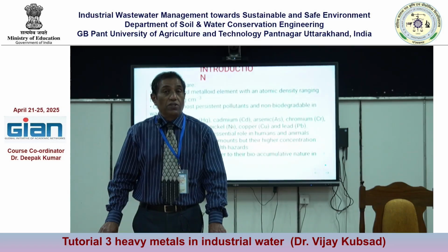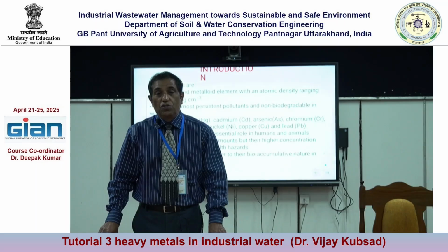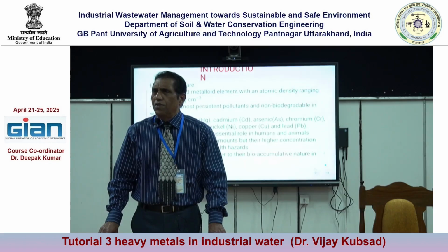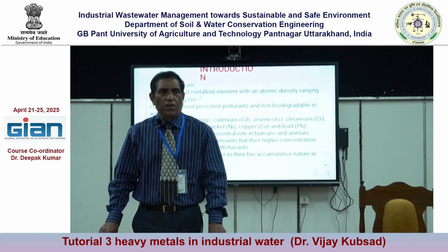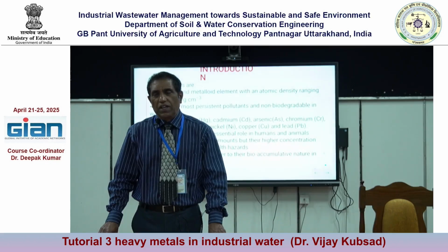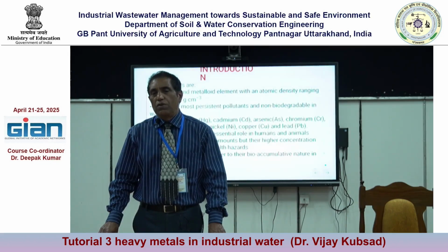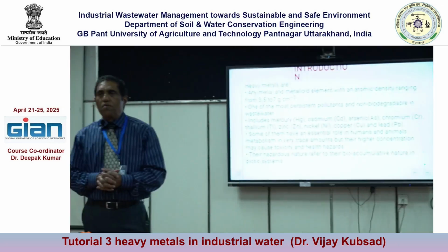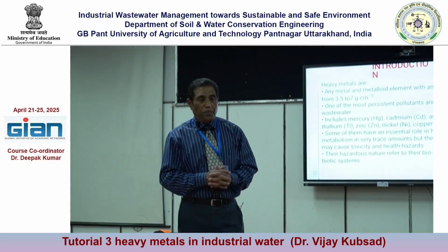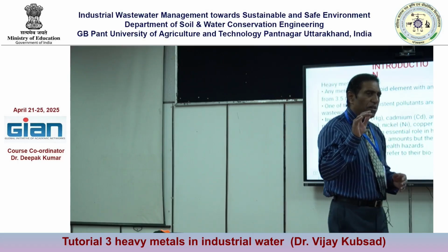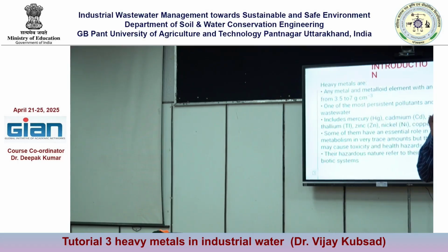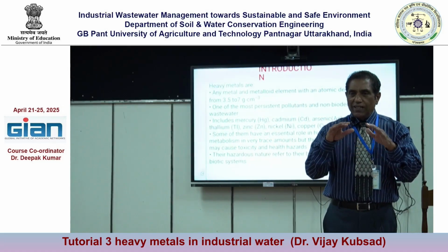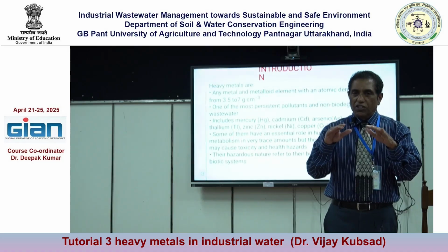Their discharge may be less, but they are not allowed to discharge it to sewer lines unless heavy metals are taken care of. Most of the metal finishers have metal issues in their discharge, but their discharge is small. In that case, we have a solution for that also. We visited a common effluent treatment plant earlier. In our earlier visit, we saw there was a removal of heavy metals, and the sludge or the settled heavy metal is collected in the tank.